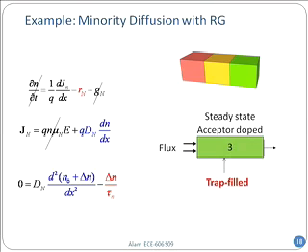If it's direct recombination, you'll put the direct recombination term in, B multiplied by delta n. So whatever it is, as I tell you from the problem, you should be able to pick it up and put it there. Now the N naught, originally before any injection was there, this was a uniformly doped material. As a result, N naught was also a constant and therefore independent of position. As a result, I should be able to take out that N naught because it doesn't have any derivative. And that's my equation. And this equation, once again, I should be able to solve.